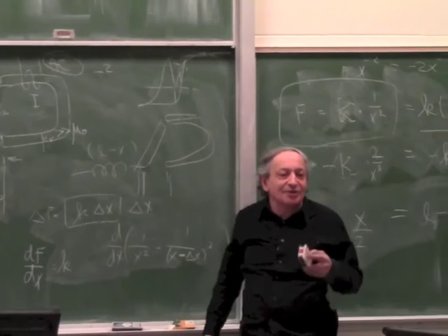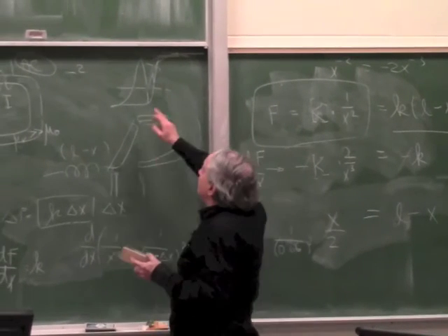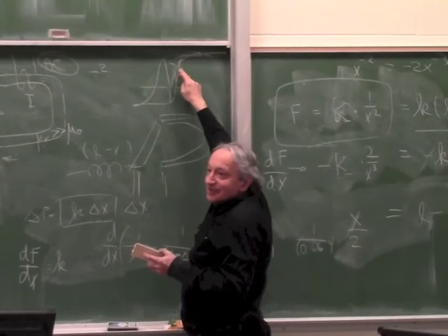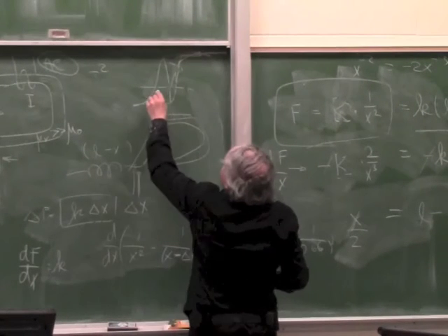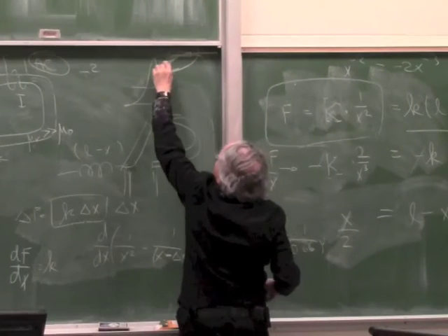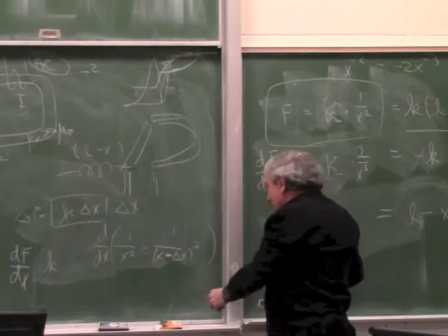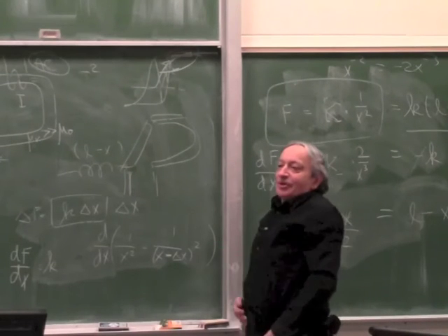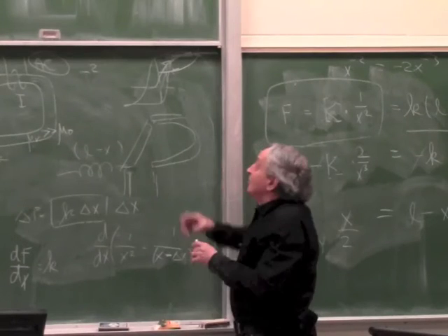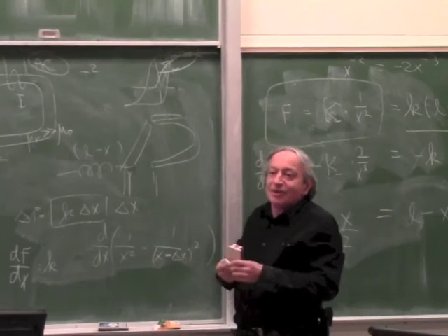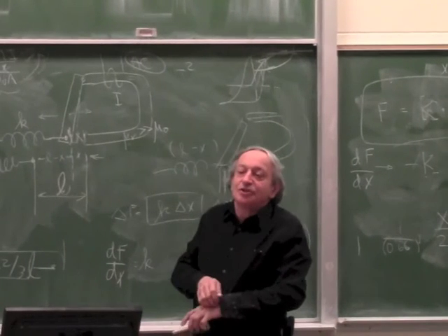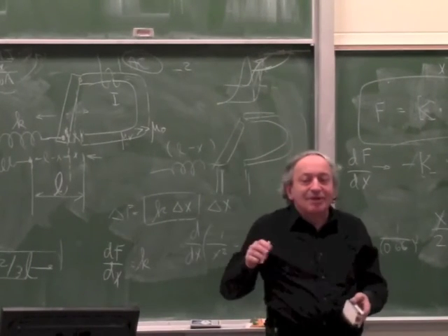It's not so simple to write a controller which, given where you are, knows the mu, because it depends how you got to this point. Right? The mu is different if you got to this point like this, or if you got to this point by coming back from here, the slope will be different. So it's actually not simple at all to say, no problem, I'll write some software which takes care of it, because it has many, many factors: temperature, which direction you arrived. So bottom line, if you really want a good servo, you can't use moving iron, except in situations where you have no choice.